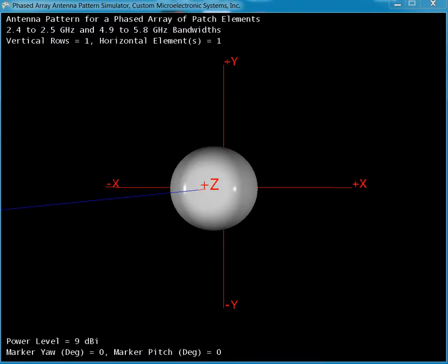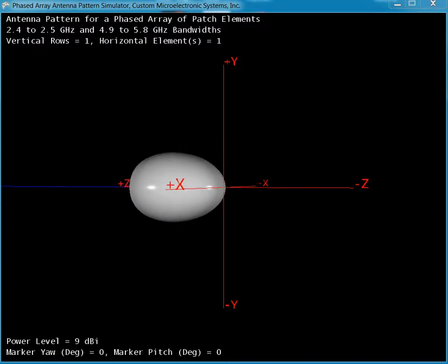And this is the radiation pattern from a single element, and it's shown in linear magnitude as opposed to log magnitude, so that as elements are added you can get a better feel for how the beam expands and becomes larger in size, how what's called the array factor forms the pattern as the phased array is continued both vertically and horizontally.